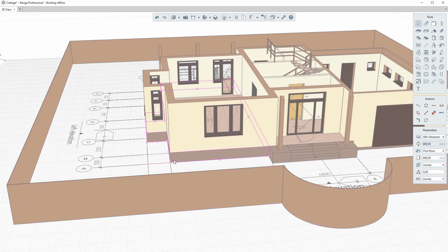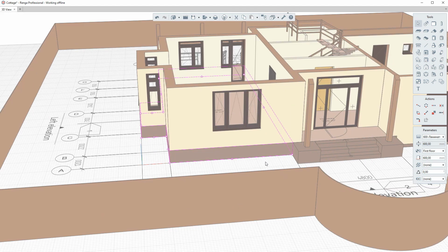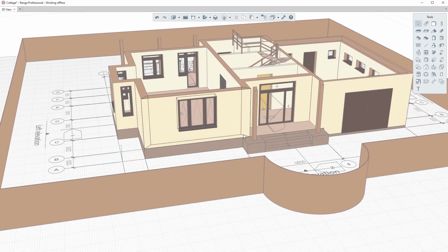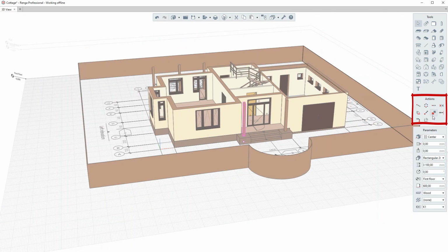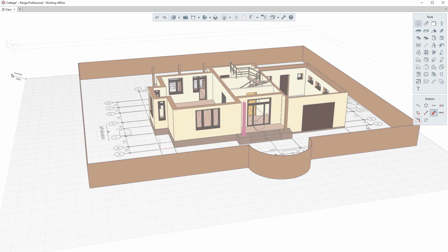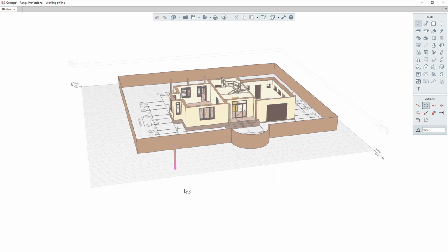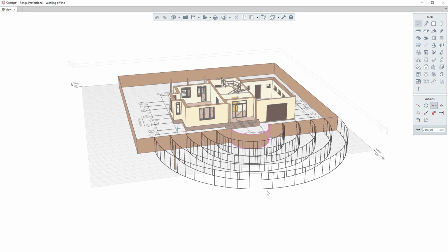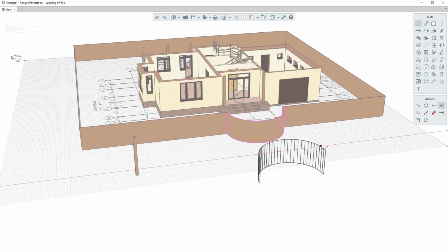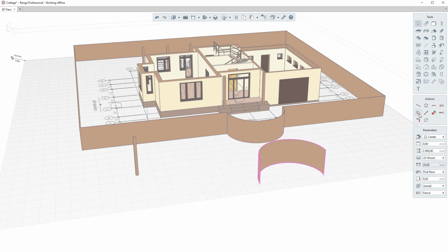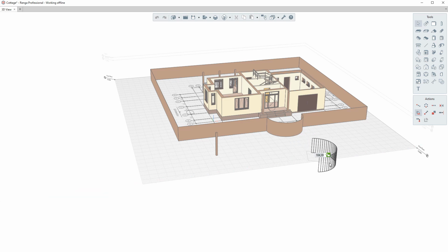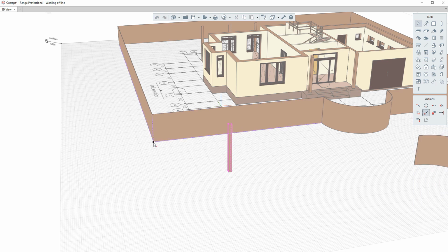The handles of the vertices and handles in the middle of the segments appear when you select Renga objects. Handles are intended for object management. When selecting objects, you can do the following actions: create copy, direct array, circular array, offset array, mirror, rotate, move.